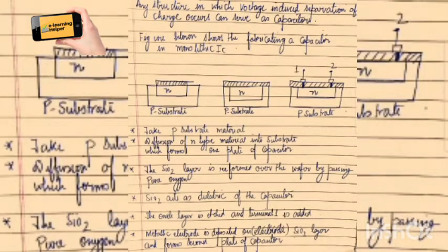Now, in the second diagram, when we form the SiO2 layer, it forms the dielectric medium above the N-type material. The oxide layer is etched and terminal 1 is added. Now, you can see terminal 1 with the metallic connection. We again etch the SiO2 layer to a certain region, and then we drop the metal into it, and terminal 1 is attached to it.